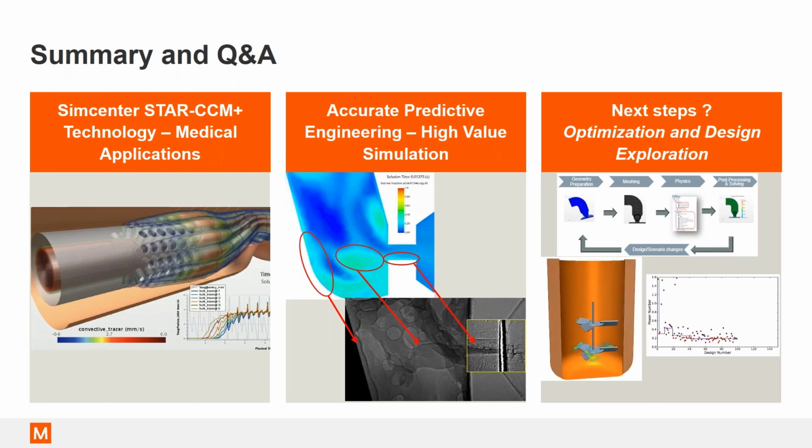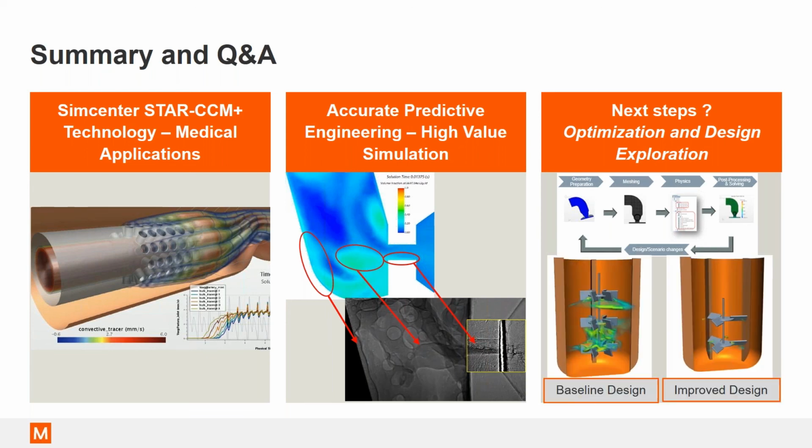So if we look at this mixing vessel here, the design is being updated by the algorithm in order to decrease the power requirements. And for that, it's changing criteria such as the number of blades, the number of mixing vessels, and the thickness or the length of the blades as well. And that is the final design that it finds out.